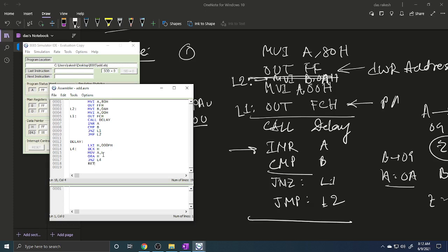So see that here the accumulator content is basically changed. So now in our accumulator there is a problem when the call instruction is executed. Our task is basically that when this increment A is done, after this call the accumulator content is again 00. So that is problematic for us.